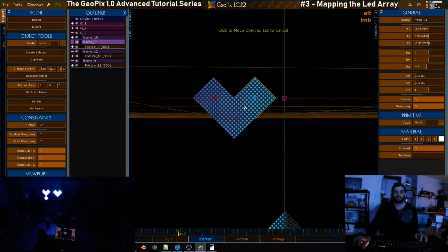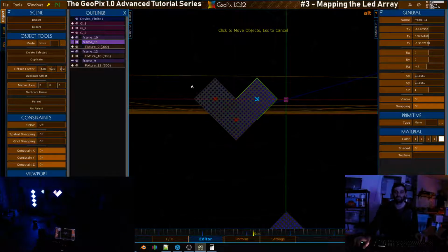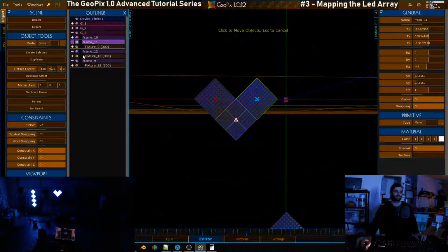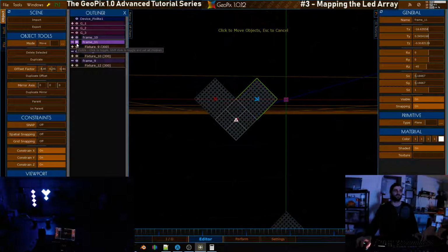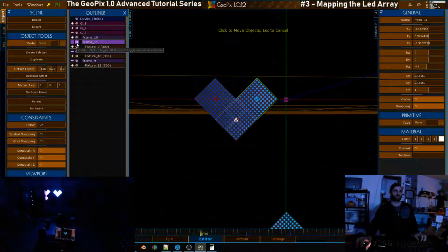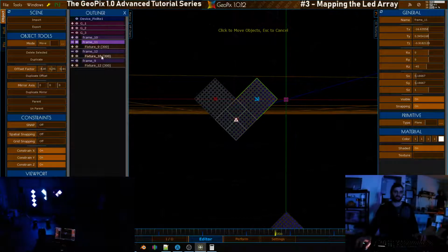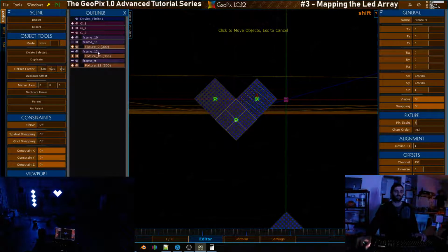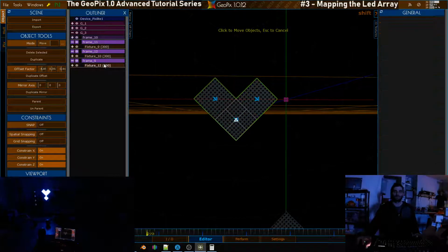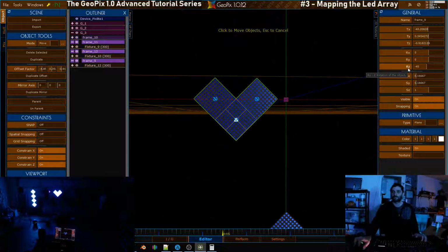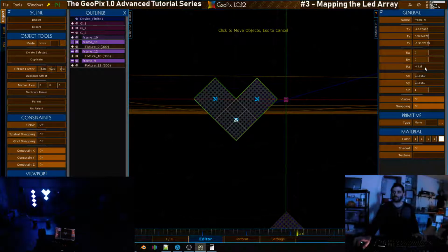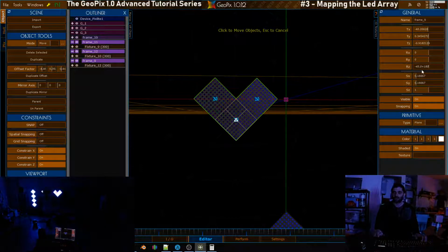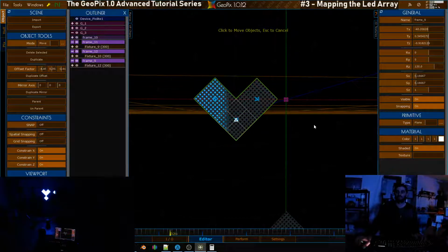Now, this is actually mapped correctly in terms of position, but you'll notice that the animation is going the wrong way, and there seems to be a staggered offset. That's because this particular cluster, this whole centerpiece, the panels are all rotated by 180 degrees, which is incorrect in accordance with the other panels, but that's fine. We can just rotate them in software by grabbing these fixtures, or the frames would actually be a fine choice as well. And for RZ, just click on the label and take -45 and just add plus 180 and hit enter, and that's going to automatically calculate the new rotations for you.